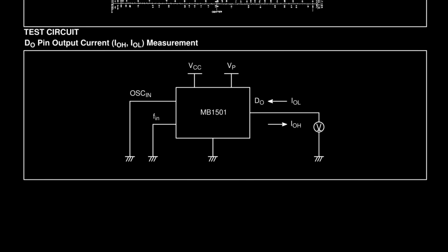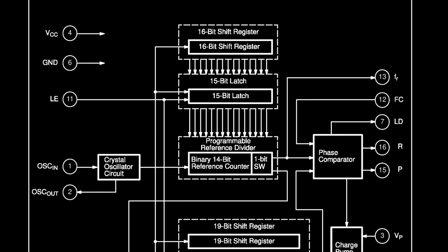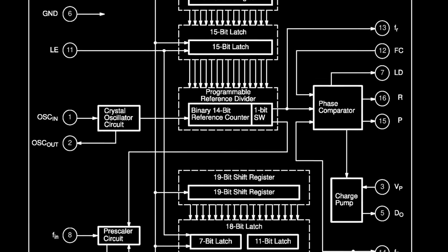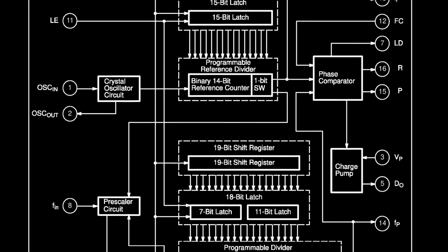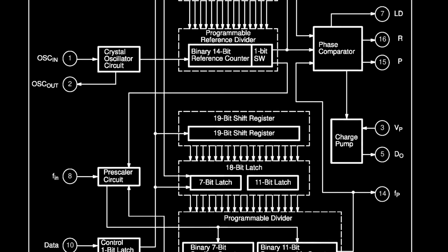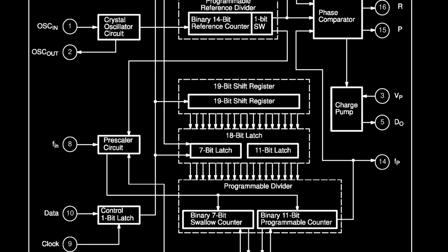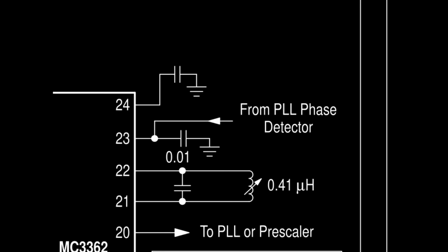The PLL takes two inputs, a resulting clock and a reference clock. Both the resulting clock and the reference clock are divided by a programmable amount first. That result is then compared. If the resulting clock is slower than the reference clock, it increases the output voltage. And if the resulting clock is faster than the reference clock, it decreases the output voltage. This output voltage goes to the voltage control oscillator in the radio chip. More voltage means faster clock. So the PLL just tries to make the two clocks equal. And the divider steps let us manipulate the resulting clock.